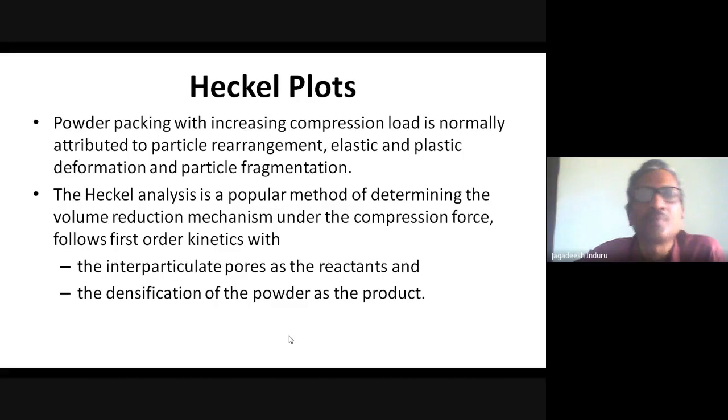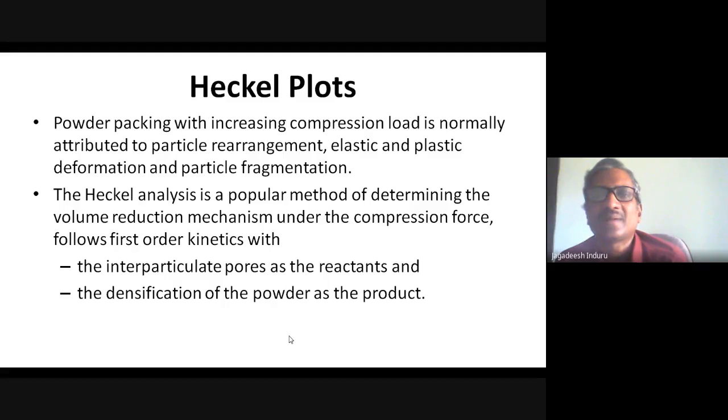Okay. Now, the powder packing with the increasing compressional load when you are applying an upper punch is normally attributed first to particle rearrangement, because when a particle is getting compressed, the voids will get filled with powders, and they are changing their shapes and sizes, and they are moving into the voids, and the rearrangement will obviously take place.